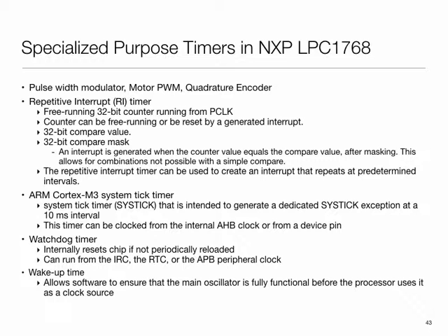Then there is another timer, the wake up timer, and this is the idea that I mentioned earlier, that the main oscillator takes some time to stabilize. Depending upon the datasheet characteristics of my oscillator, I can program this value. So when I start out, after a little bit of reset delay, 60 microseconds, we start operating off the internal oscillator, and then once the wake up timer kicks in, we switch the clock to the external oscillator, and now I have a more stable clock source. All of this has to be done by the OS. As you can see, a lot of attention.